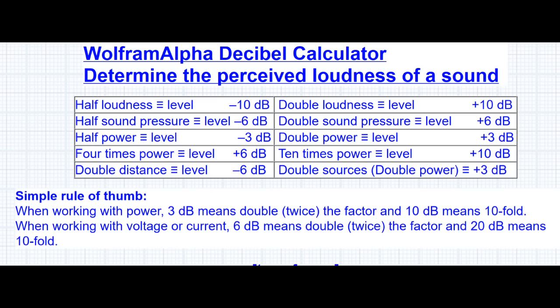For instance, if you've got a light bulb 10 feet away, it's a certain brightness. 50 feet away, it's a certain brightness. Same thing with sound pressure. A couple rules of thumb is that if you decrease the sound by 10 decibels, that is half the perceived loudness for most people. So if you want 1/4 of the noise that you're now hearing, that is a 20 decibel reduction.